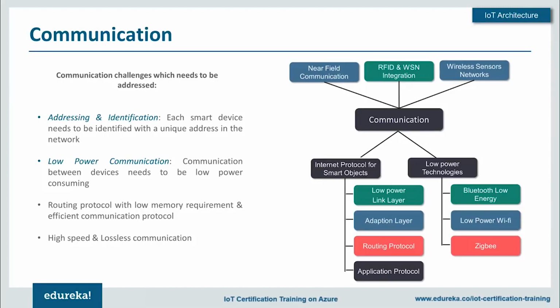We'll talk about the next segment, which is your RFID and WSN integration for smart objects. Many times, what you need to understand is that data from one single sensor is not useful for monitoring large areas and complex activities. Here, you're going to use various sensor nodes to interact with each other. Again, this also has to happen wirelessly. Now, the disadvantage of a non-IP technology such as RFID, NFC, or Bluetooth is that its range is very small, so they cannot be used in many applications wherein a large area needs to be monitored through many sensor nodes deployed in various locations for that matter.